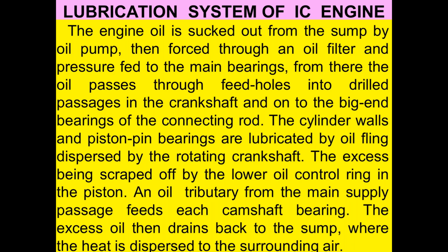Lubrication system of an IC engine. The engine oil is sucked out from the sump by the oil pump, then forced through the oil filter and pressure fed to the main bearings. From there, oil passes through feed holes into the drilled passages in the crankshaft and onto the big end bearings of the connecting rod. The cylinder walls and piston pin bearings are lubricated by oil flung by the rotating crankshaft, the excess being scraped off by the lower oil control ring in the piston. An oil tributary from the main supply passage feeds each camshaft bearing. The excess oil then drains back to the sump where the heat is dispersed to the surrounding air.